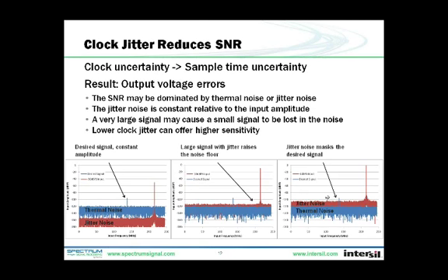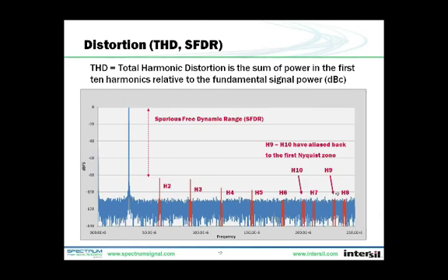In a traditional receiver, the interfering signal would be removed by a filter, but since SDR processes a wider range of frequencies, that's not practical, and you have to have more dynamic range to handle the wider amount of spectrum that you're digitizing.